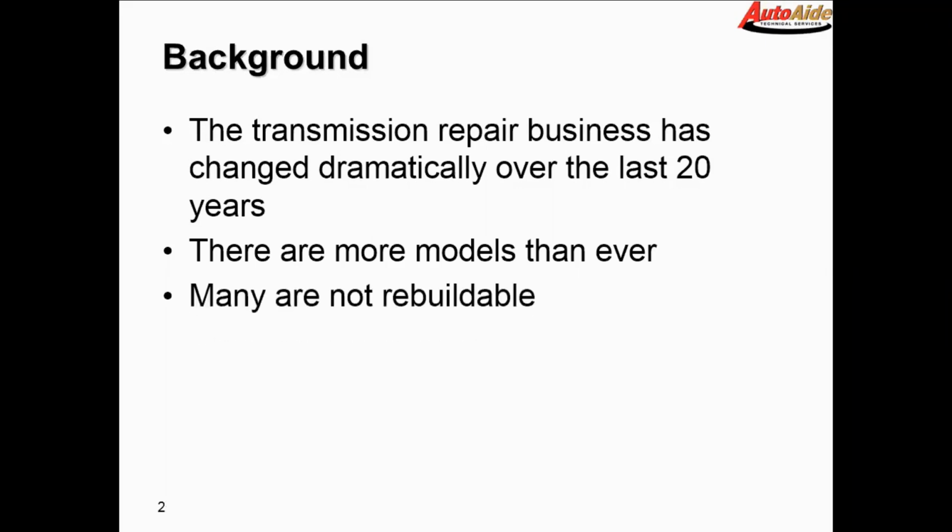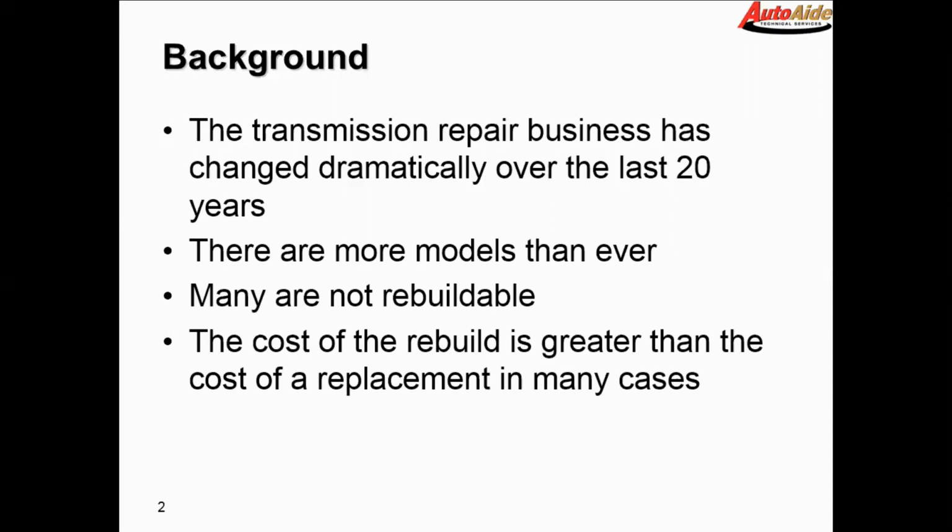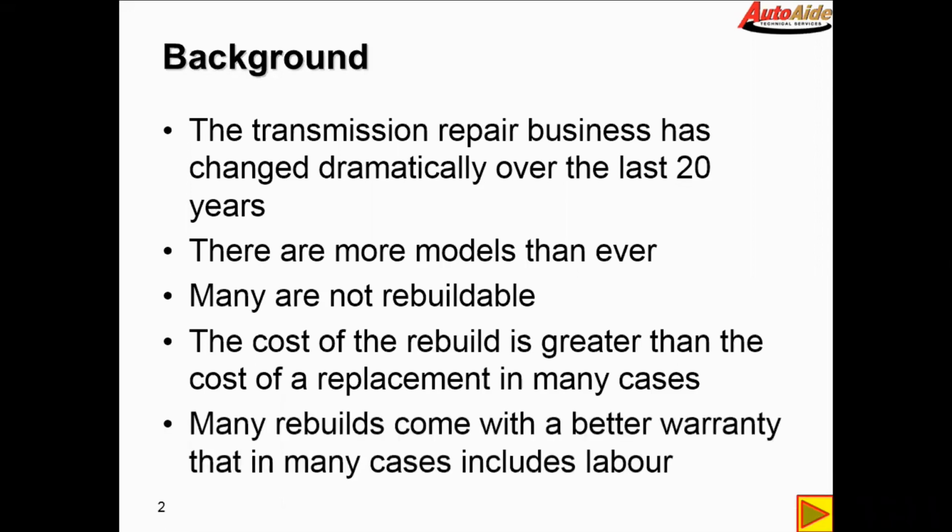And to add to it, a lot of them are not rebuildable. And in a lot of cases, the cost of rebuilding one is more than the cost of a replacement. You can get a dealer drop-in with a good warranty on it for less than you can actually overhaul the darn thing yourself. And in a lot of cases, they come with a better warranty. So there's a lot of pros and cons as to how you're going to go about fixing it. But you do need to do a little bit of research when you're calling for a box.